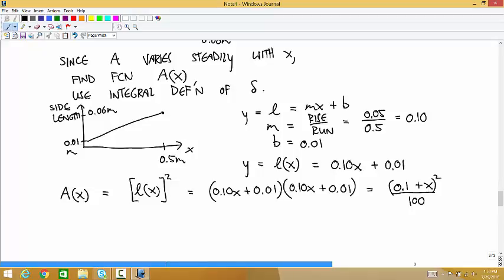I didn't do this, but you need to check that this meets that 10-degree requirement. You can do that with what? Inverse tangent. So the inverse tangent of 0.05 divided by 0.5, that's going to be way less than 10 degrees. So this is fine. It doesn't look like it the way I have it drawn here, but that's a small angle.